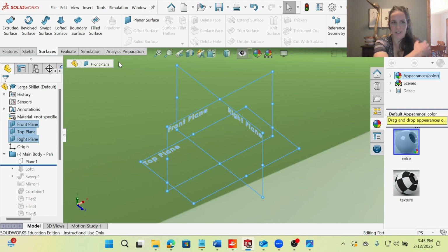So we're going to start off today with a reminder that your submission for next week will be expected to be oriented and built with the front plane, the right plane, and the top plane as your main references. And the reason for this is so that you can easily mirror and work around those planes in terms of mating it in an assembly down the road. But it also just gives a really nice opportunity to make sure everything in your design is symmetric.